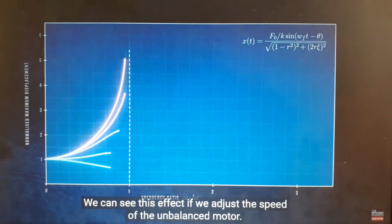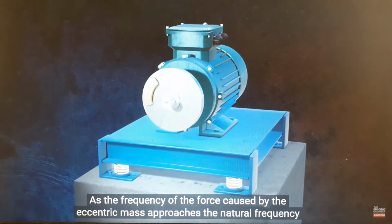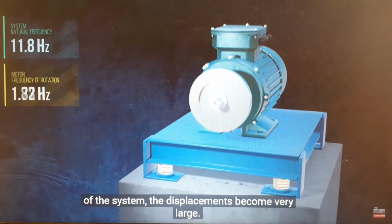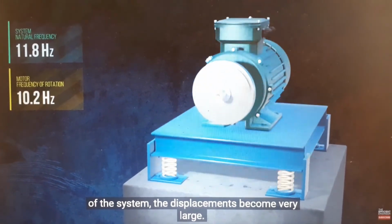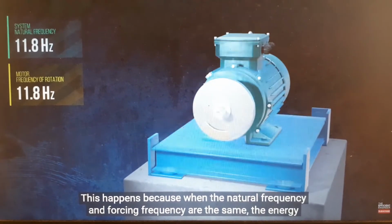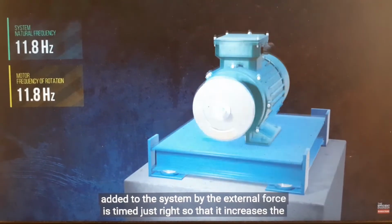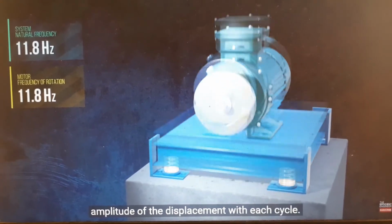We can see this effect if we adjust the speed of the unbalanced motor. As the frequency of the force caused by the eccentric mass approaches the natural frequency of the system, the displacements become very large. This happens because when the natural frequency and forcing frequency are the same, the energy added to the system by the external force is timed just right so that it increases the amplitude of the displacement with each cycle.